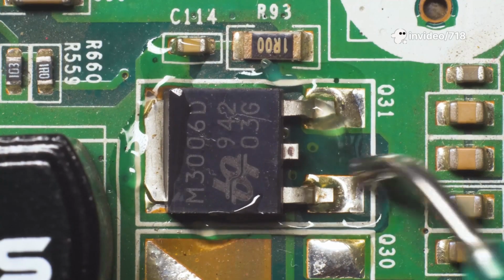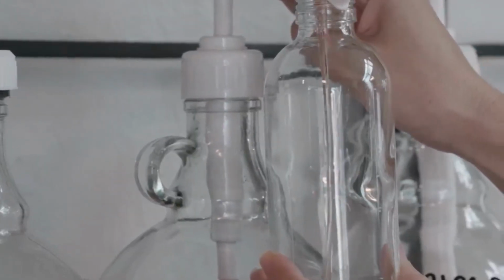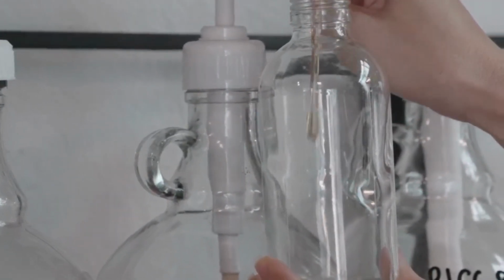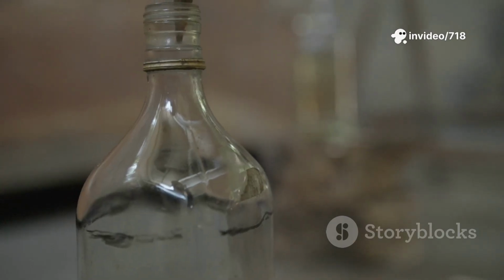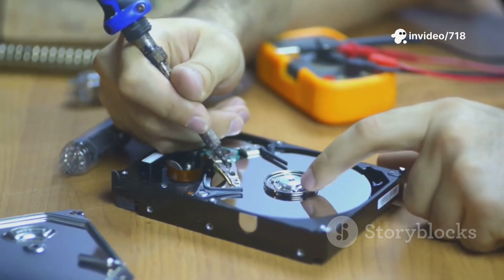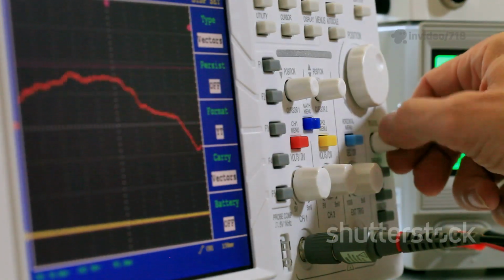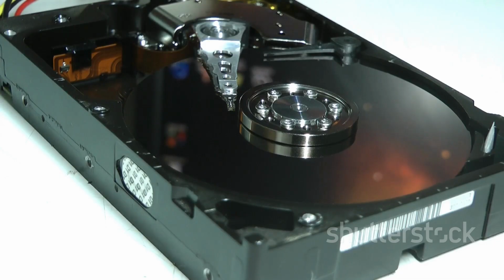This is a fundamental property of the one transistor, one capacitor design. It's like finding out what's in a bottle by pouring out its contents. You know what was in there, but the bottle is now empty. To solve this problem, the DRAM has to perform an immediate restoration. After the sense amplifier reads the value, it doesn't just switch off. It actively writes the value right back into the cell it just read from.